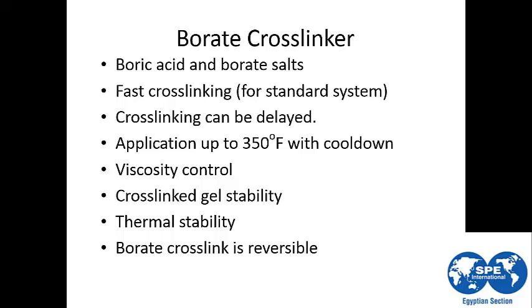Its advantage is fast crosslinking for the standard system. We can delay the crosslinking time in order to reduce the wellhead pressure if we are going to pump through high lengths or fracture deep wells.